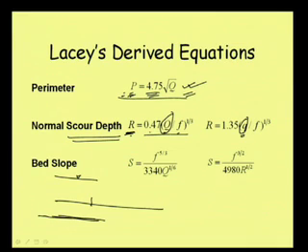And if we are constructing a hydraulic structure here, and the water erodes up to this much depth, the hydraulic structure will not remain, it will be washed away. So, we will have to provide some provision, say putting a barrier here, so that even if the erosion comes to this depth, it will not take the hydraulic structure away, and this is called a cut-off. And for designing those we use this scour depth.